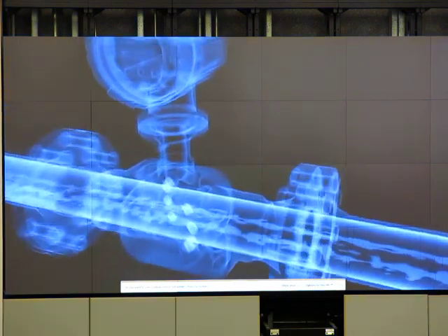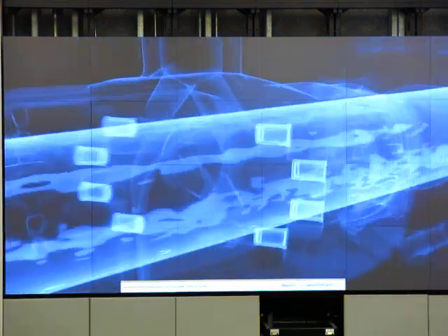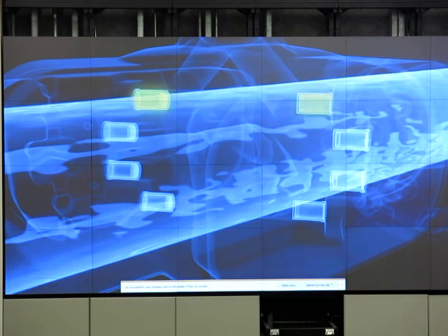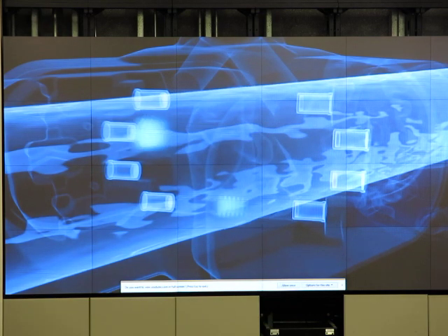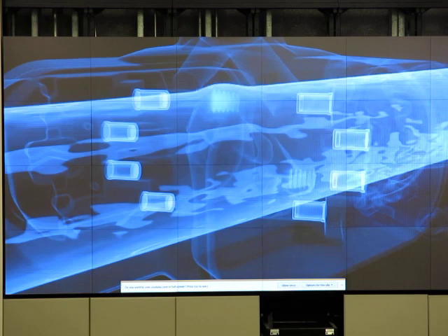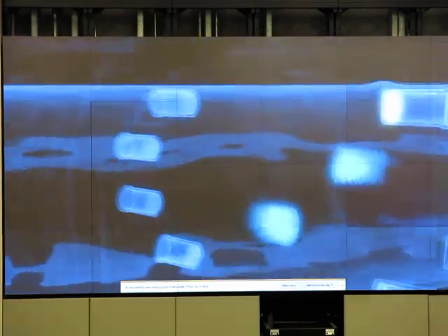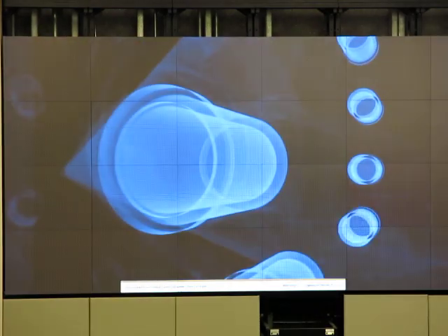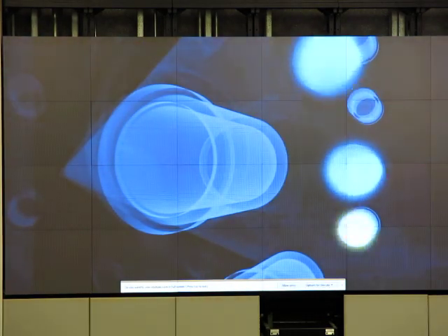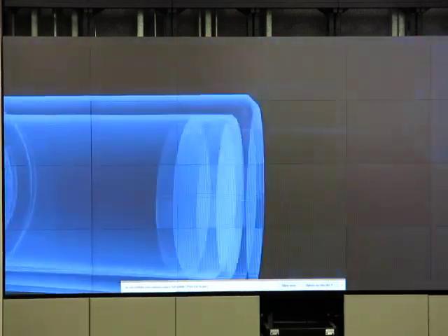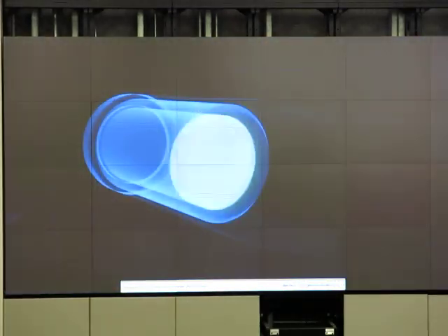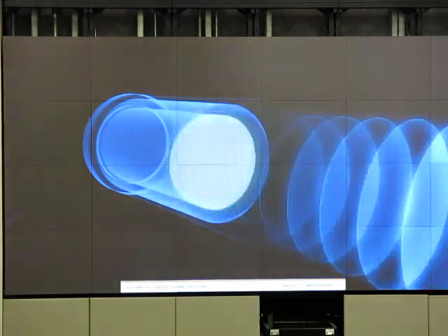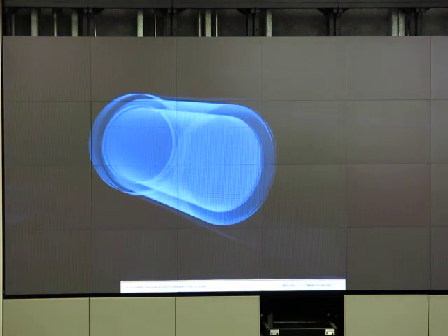Inside the ultrasonic flow meter, pairs of sensors are fitted across from each other in the measuring tube. Each sensor can alternately transmit and receive an ultrasonic signal. Simultaneously, the transit times of these signals are measured. The ultrasonic signals are generated with piezoelectric crystals applying a voltage. Conversely, a piezoelectric crystal creates a voltage when an ultrasonic signal impacts the sensor.